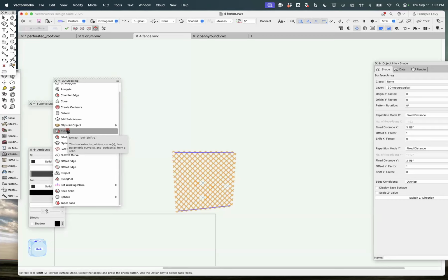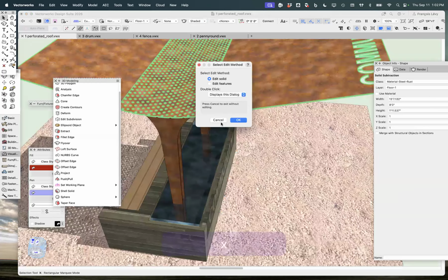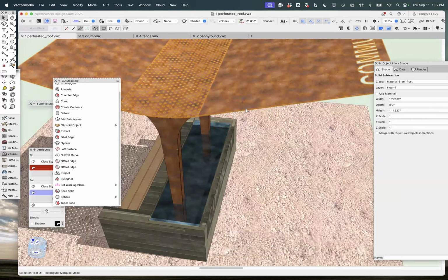Well, that's strange because in your very first example with that curved steel, that seemed to have a thickness. Nope. The thing that I subtracted from that has a thickness. Yes. But you'll remember I extracted the NURBS surface of the top surface of the curve. Ah, okay. And I used that as my array surface. Right.